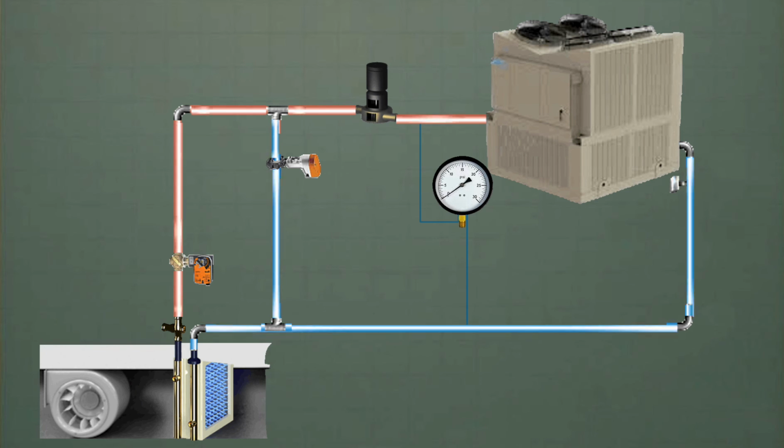The real problem here was the bypass valve. The bypass valve was dramatically undersized. It's actually quite common. There's issues with the bypass. Sometimes it is undersized, sometimes the timing is off. Maybe they'll have a quick response valve for the air handler, so the air handler will shut down immediately, but the bypass valve takes 90 or 120 seconds to fully open, and before it fully opens, the machine will shut down or lose flow. So sometimes you might have to adjust the timing in the automation system in order to get your machine to not trip on flow. But it is quite a common problem, especially on newer startups and newer machines.